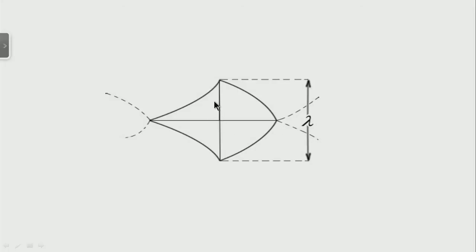Therefore, a detonation wave is a multi-headed structure, and this cell of a detonation is very characteristic. We say, well, this is the length of a detonation. The width of the detonation cell is called the cell size of a detonation, which we characterize by the letter lambda. To sum up, a detonation wave is not something beautifully one-dimensional.